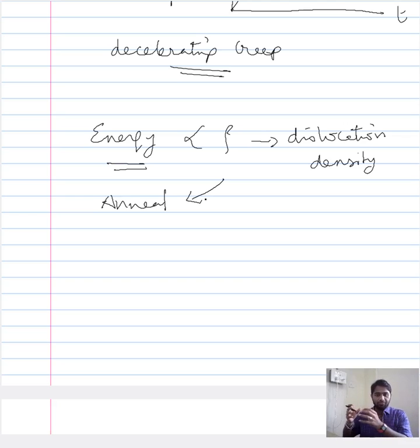So now, when you talk about cold working, wherein you just impose a plastic deformation, you increase the dislocation density of the material, and now you want to reduce the overall energy of the system to a certain extent, and then you anneal it. So what is essentially happening in the annealing is you increase the temperature of the material. That is nothing more you would do. You will not introduce any phase transformation or anything like that. You just increase the temperature of the material.